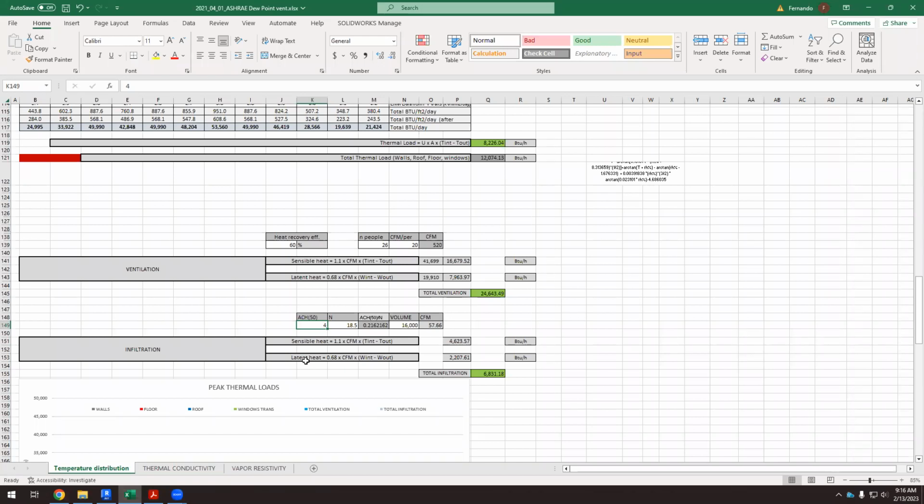Okay, so it's impossible. In this building, what's the infiltration in this building? I don't know. I have to do that test because it's not something calculated, because it depends on how it is. If there are cracks between the walls and the windows, the infiltration will be terrible. If the construction is perfect, the infiltration will be very low. But we can't calculate that. We have to test it in the real building. Okay, so Revit has taken into account that infiltration.